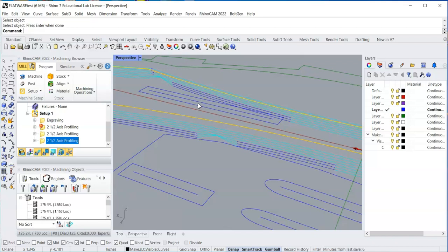Okay, but sometimes I don't. Oh, this is horrible. I shouldn't tell you this one and record it. Sometimes I don't want to have to file those tabs off the inside. So what I'll do is, as I'm cutting on the machine, I'll stand there at the machine and I take a wrench and I put the wrench on the part that's getting ready to fly out, and I put a lot of pressure at an angle. I hold my wrench and I put pressure up here on the wrench, and it keeps that in place as it finishes the cut. Then it lifts out, goes to cut the outside, and then I can reach in the machine and pick that out, okay?